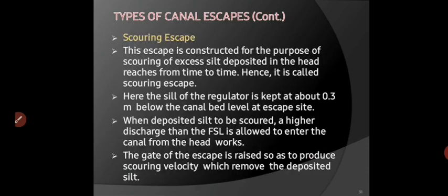Third is scouring escape. This escape is constructed for the purpose of scouring of excess silt deposited in the head reaches from time to time. Hence it is called scouring escape.